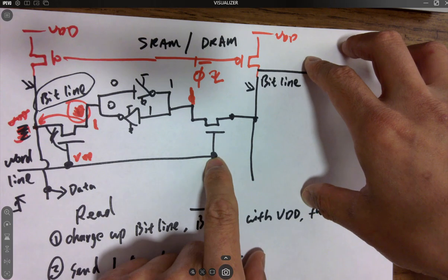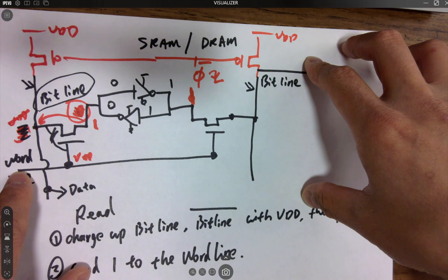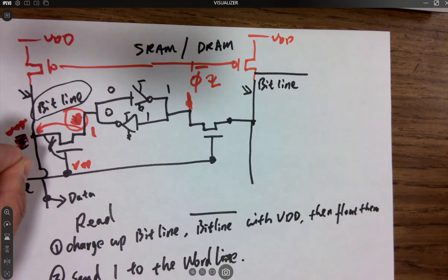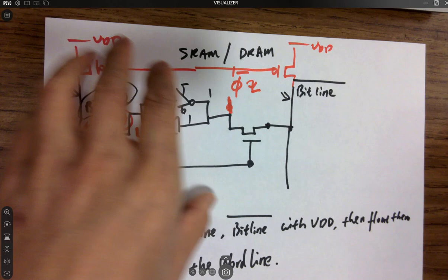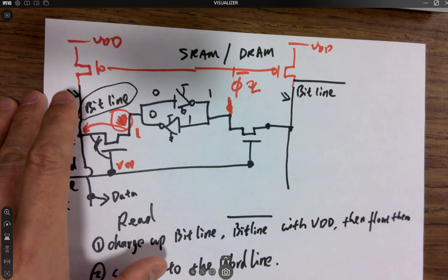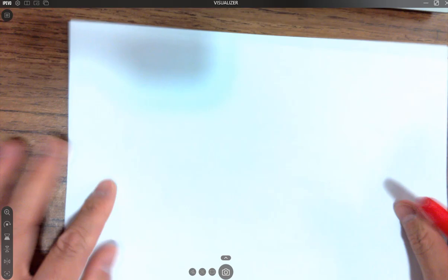You just extend this word line. Whenever this word line hits this port, it's going to turn on all the bytes in the line, so you can read and write for the bytes at the same time. It's doing 8 bits at the same time, and it's just 1 cell. That's for SRAM. So reading and writing requires a little bit more circuitry over there.